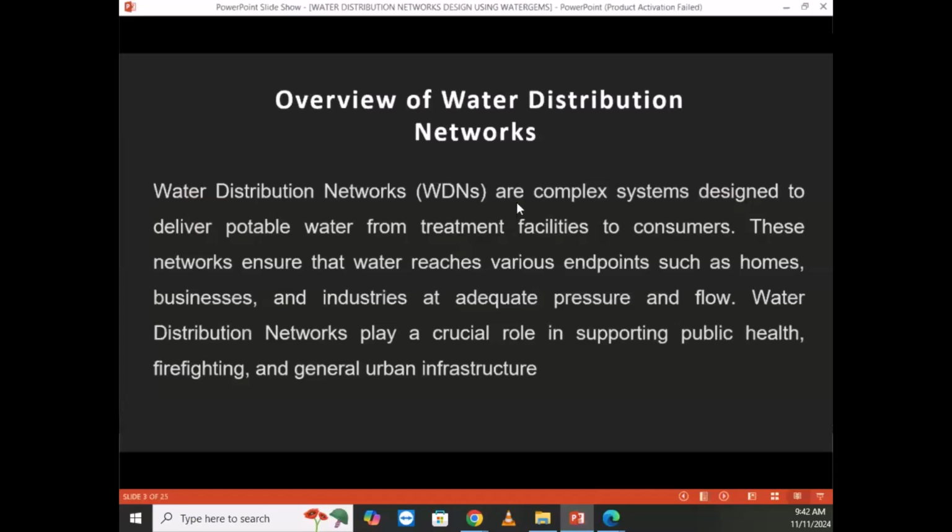So it's better to put this treatment plant at the source, treat your water, and then pump your clean water. But this is for the place where your source is at lower elevation, compared to the location that you want to supply your water.